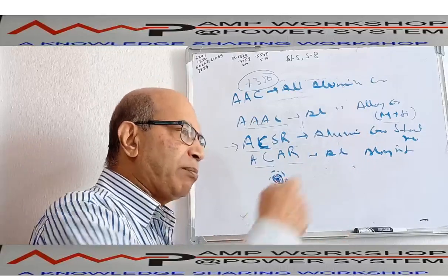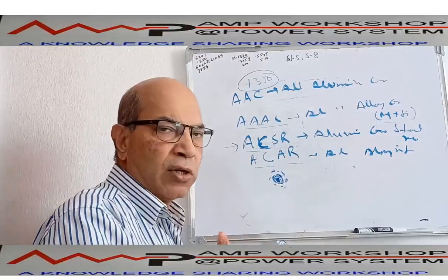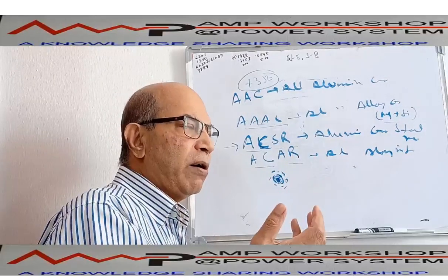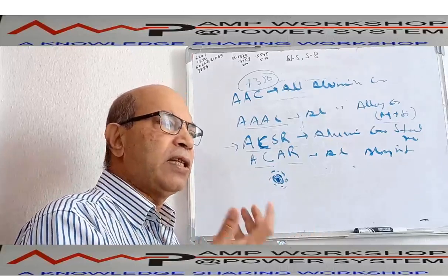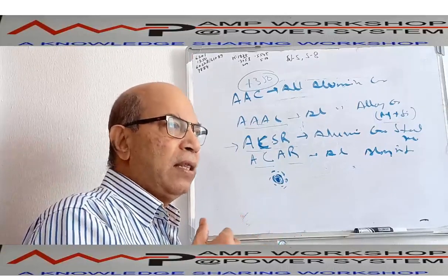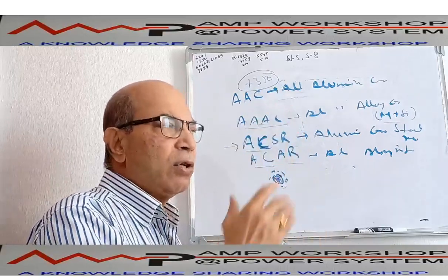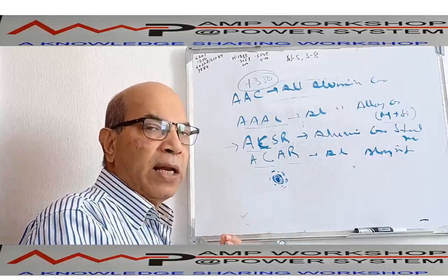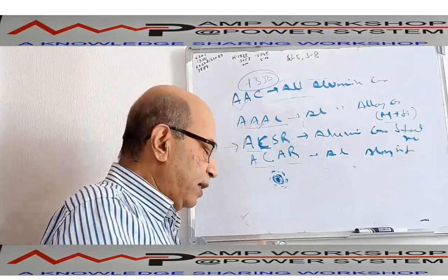But if the span between two towers is not very long, as in rural distribution, or in an urban city, though we use cable there, in some urban or suburban areas you can see overhead conductors. In urban or suburban areas, houses are continuously one after another, so the tower distance is very small. In that case you don't need more mechanical strength, and we can use the all aluminium conductor, or AAC conductor.